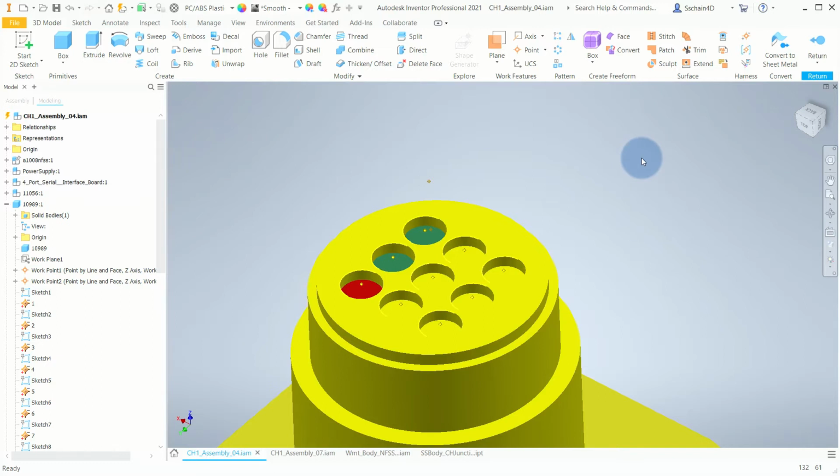Then I need to add a reference designator placeholder. It's an identifier that maps the part to a schematic design. You generally add a placeholder such as U question mark. The question mark represents the associated occurrence in the assembly and is replaced by a number. For example, U1, U2, U3 would add a unique identifier for each instance of that connector.